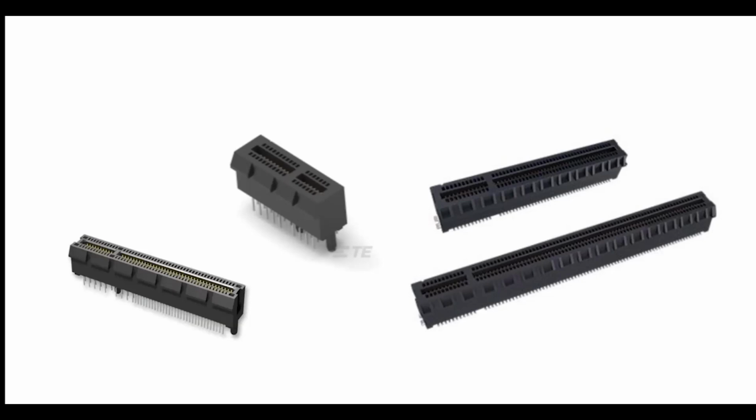And that's what's inside a modern computer. The bit to the left with the 22 pins contains the power, the interrupts, the chip selects, the clocks, all those housekeeping, controlling sort of parts of the interface. That's what those 22 pins are. And then the bit to the right is one or more PCIe lanes.